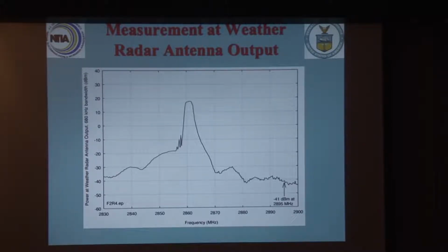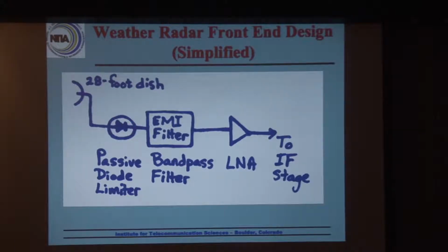Frank, I see the problem with that picture: you put that limiter in front of your filter. I mean, you're exposing it to a much broader band of frequencies, and hence much more severe nonlinearity. Well, that's another good point that you bring up, Bob. By putting the limiter here, it sees all the energy in all the world at basically all frequencies from virtually zero up to however high this responsive microwave part of the spectrum. Well, actually, the waveguide cutoff would terminate it below a certain frequency. But anyway, yes, it sees a lot of energy. Now, if you put it over here, it would only see the energy that would come through the EMI filter. And of course, that's the energy you worry about getting into the LNA, and that's really the energy that you want to limit. So that's another reason to put it there. We'll see a third reason why this limiter should be here and not here.